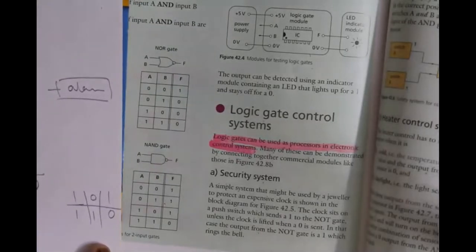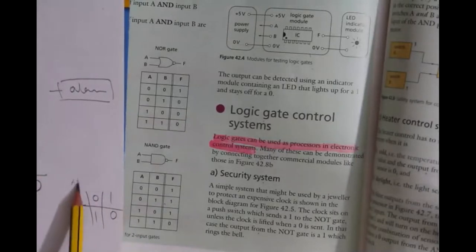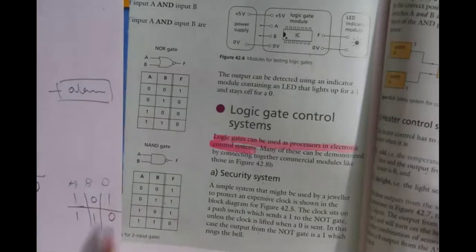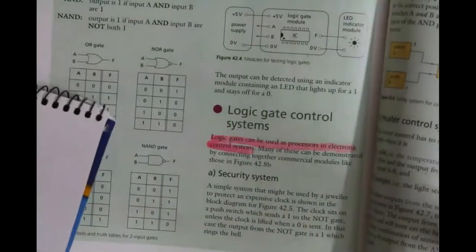Yes. Okay. So over here, this is the input, A, B, output. Okay, so 1 0 1. That's what we wanted. 1 1 0. So it looks like the NAND gate is gonna work for us. So we're gonna draw NAND gate, and that's the gate we're gonna use for this diagram. Okay, let's move on to the questions.